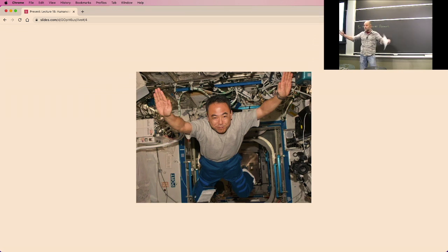That is always true. This is a complicated humanoid, but the center of mass dynamics are very simple. When you add gravity, it's still simple; it happens to be that you're pulled into the ground. But the abstraction of what your center of mass must be doing seems more clear in my head when I think about an astronaut in space moving around. So that's the secret: even when the robot has many links, the center of mass dynamics are still simple.